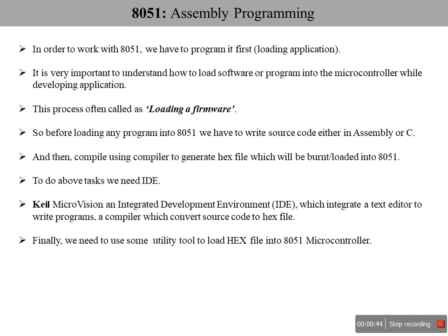In order to work with 8051, we have to program it, or load an application. So it is very important to understand how to load a program into a microcontroller while developing an application. First we have to write an application. That application should be burnt or loaded into 8051. This process is often called loading a firmware into a microcontroller, or to be specific, burning a firmware into 8051.